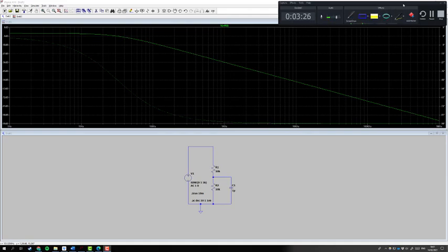So let's get our pen into action here. A dB, just in case you don't know, is minus 20 log of I1 over I2. So your new frequency compared to your original. And we use dBs for gain because gain tends to be a logarithmic process. And we normally say that the cutoff is at minus 3 dB.